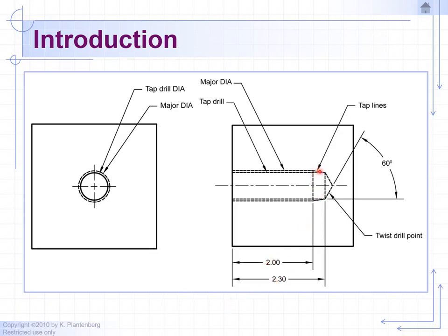And then you go beyond, and this is where it starts tapering. And then we have this V shape due to the drill. So for the tap that goes in here, first you'll drill a small diameter hole, and then you come in and tap it. So this represents the end of the drill, which has a conic shape. It's just easier to scoop material by having a conic end on the drill.